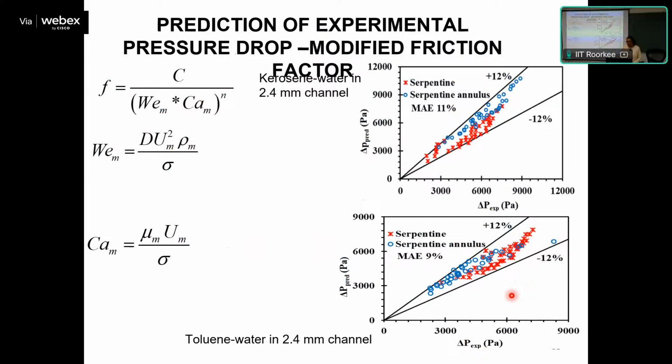Of course, similar correlations are reported for air-water in miniature geometries. So it is not a function of Reynolds number alone, but of something more, where the surface tension, the interfacial tension, comes into the picture. In that way, we have taken into account the Weber number.